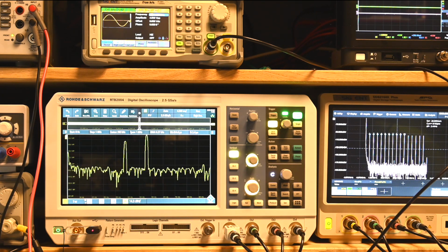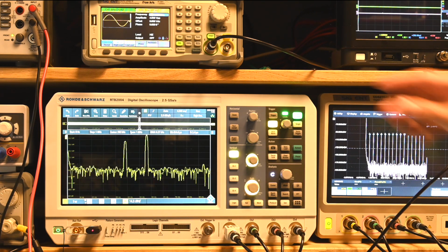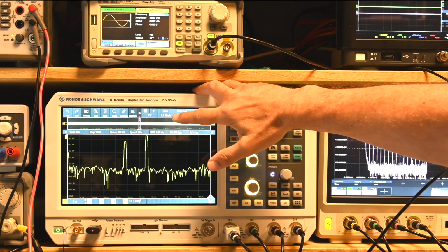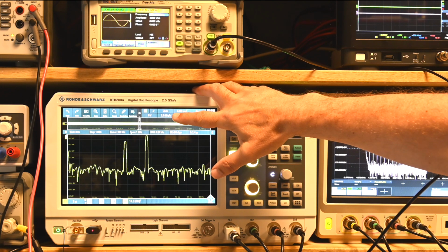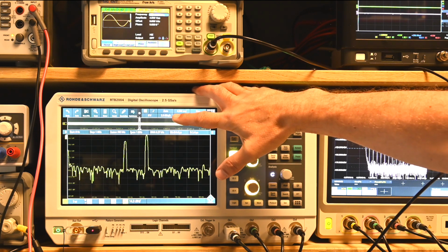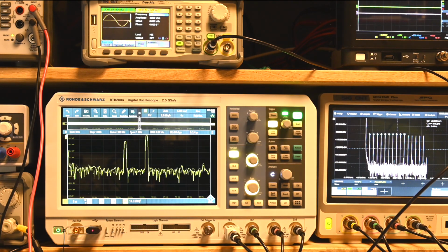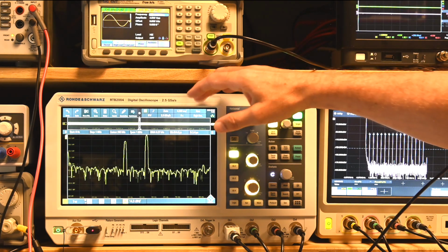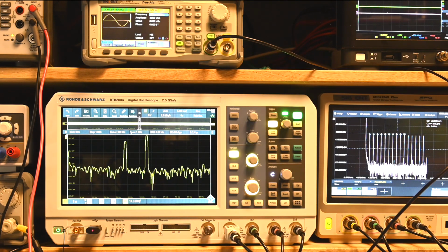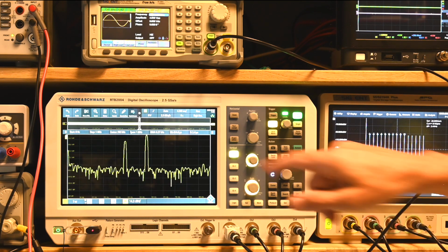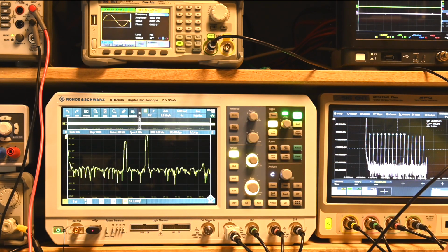So by doing this, I am confirming that the sample frequency of the FFT procedure is indeed the 2.5 mega samples per second we see here. So this is not only the time-base setting, but now I know this is actually the current FFT setting. And that was the big question we were having, because earlier we were wondering whether the sampling frequency, and thus also the Nyquist frequency for the FFT mechanism, would perhaps be different in some settings from the time domain ADC settings, and that would explain the mystery. But now I know for sure that in this particular setting it is the same.